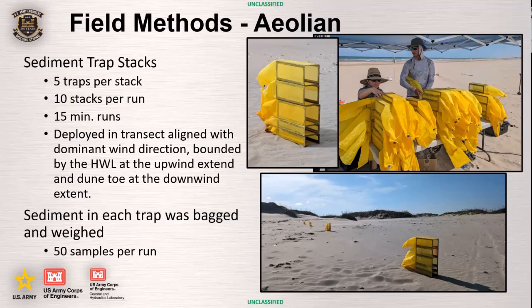When the traps were open in the field, they were open for a time period of about 15 minutes. This is pretty common within the aeolian literature for getting a robust measurement of what that sediment transport rate is if you were to back calculate it out to how much sand is moving per second. And I should also note that these traps are oriented into the wind. So that transect, if wind is coming from a consistent direction, then that transect will not move. If it's moving around during the course of the study, that transect will also follow suit and move as well.